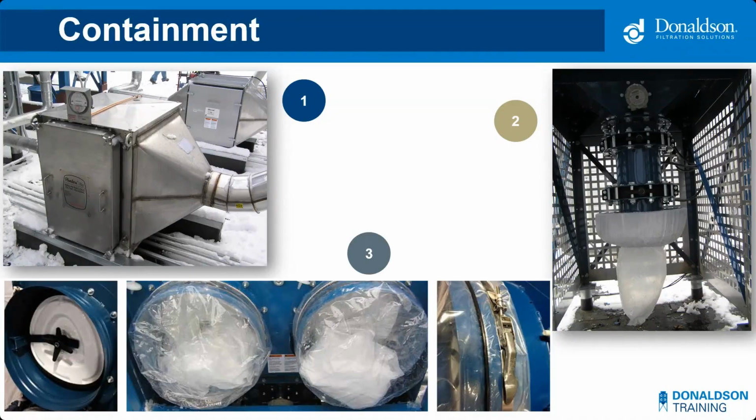And then probably what I would call one of the most important is photo 3, and this is our bag in, bag out design configuration, which allows you to go in and change the dirty filters without ever coming in contact with the dust. You work everything through that plastic, and you can actually pull the filter right into it, tie it off and wrap it up, and greatly reduce your exposure when doing dirty filter changeouts.